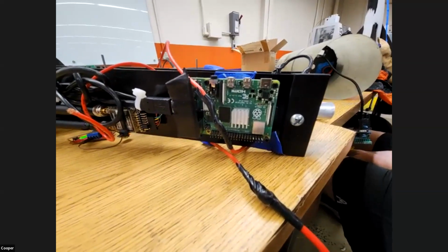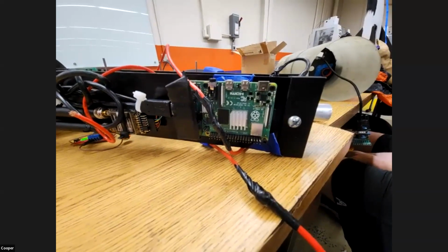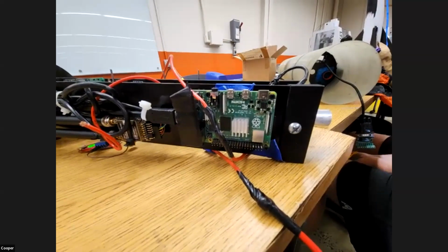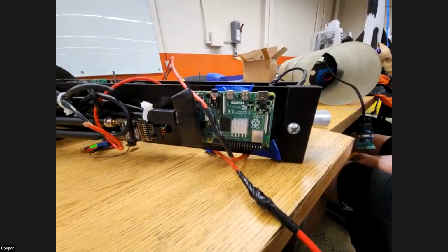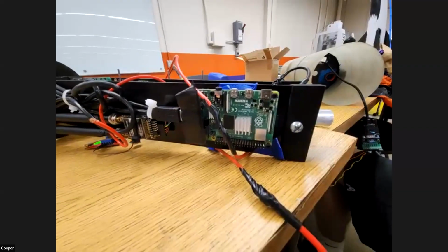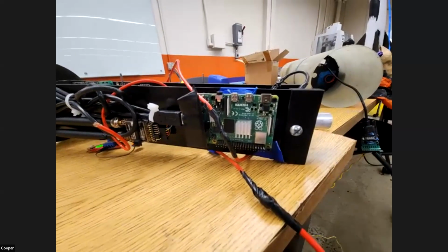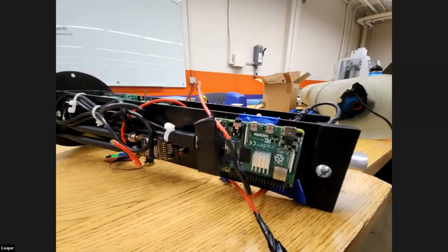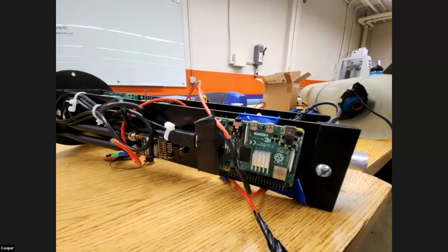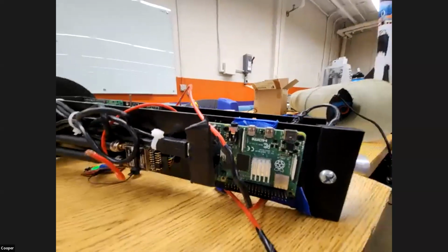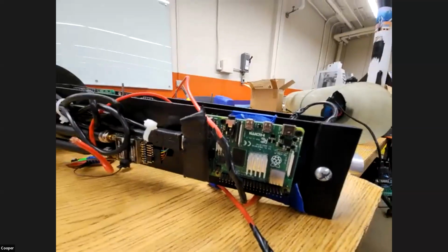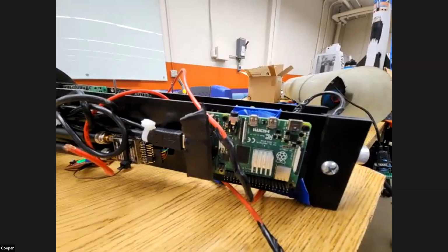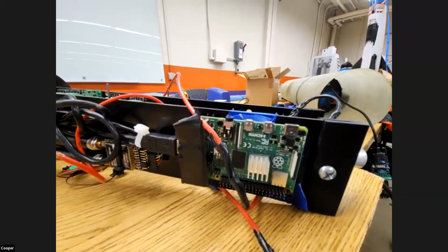What are you using for your filtering logic for that? So a lot of the components we're using are breakout boards that do a lot of that filtering on board, the SOM, system on module. So it deals with a lot of that for you. By the time it gets to the flight computer, it's actually pretty decently filtered for accuracy and precision. But we still do some onboard. We take a lot of medians between data ranges, so that we can deal with outliers in data and not overreact to certain measurements.